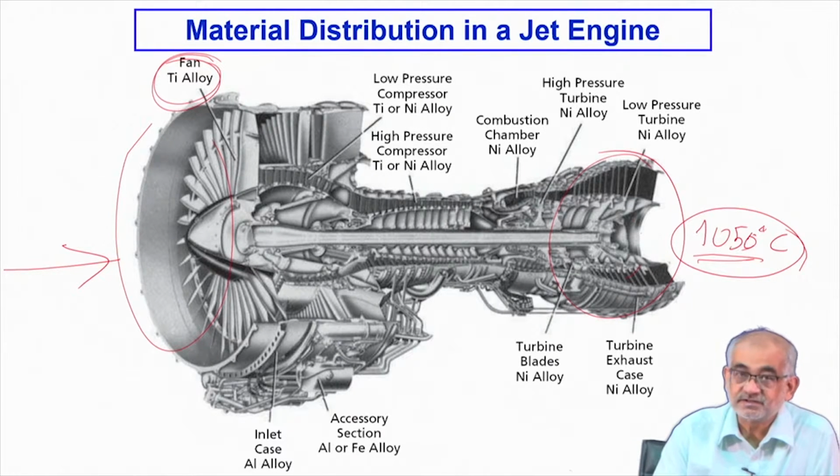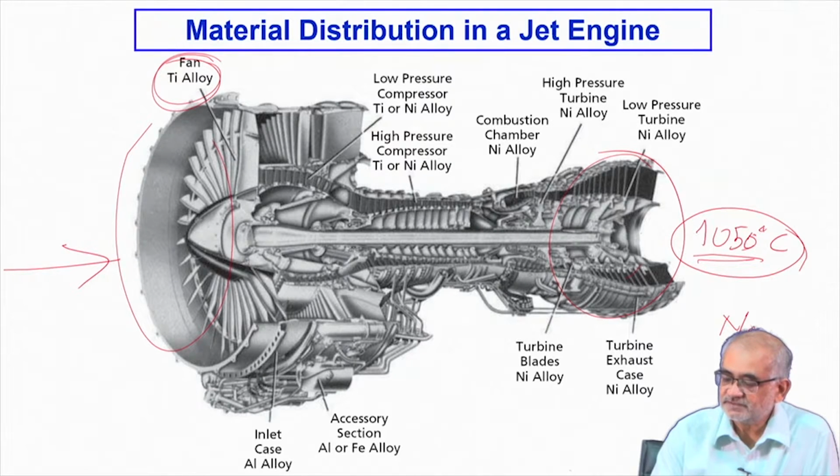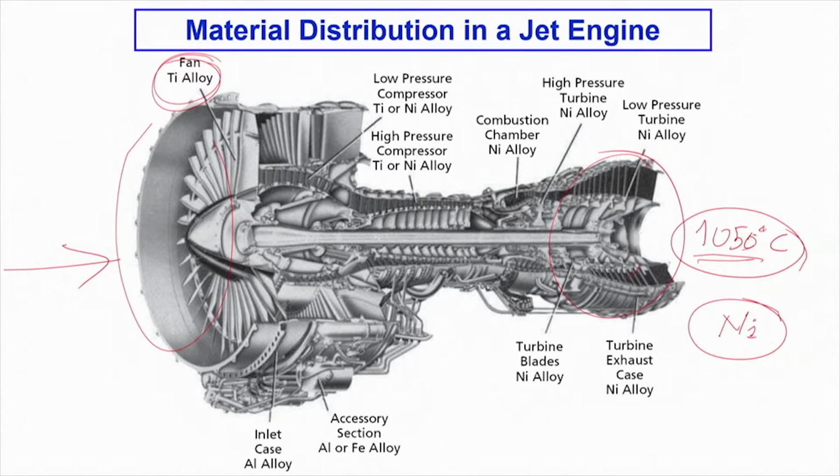Now when you want to prevent oxidation of nickel based superalloy, you have to realize that if the body is made of some nickel based alloy, then on top of that ideally you would like to have coatings of, let's say, zirconia. Now zirconia, obviously if it can bond well with nickel, there is no problem, then it can prevent counter ionic transport. For nickel to undergo oxidation, you require the cations, the nickel, to go out and the anion, the oxygen, to come in. So if you can create a barrier here in the form of this zirconia, then these nickel ions or iron ions are not able to go and meet the oxide ions coming from the air, and hence the oxidation can be prevented.